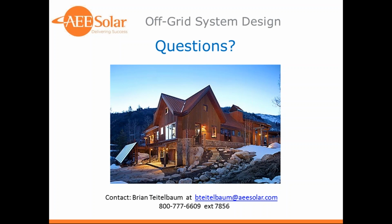Well, this is something that comes up from time to time. The idea of a 50 amp outlet is an idea that there's unlimited energy there. And really, we can't just look at a 100 amp service panel or a 125 amp service panel or a 50 amp service panel and just design to that. We really need to look at what the loads are.